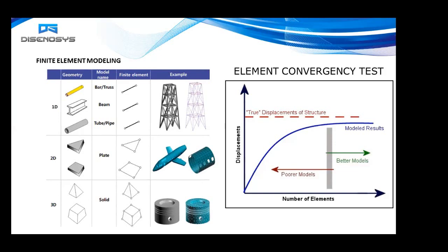Oh, okay, sir. You can't actually cover all the geometry using shell elements. So as we have seen in our example 2, how much you have covered that area, then only your accuracy is increased. So you have to cover your shape initially. How much the possibility of covering the shape will give much better accuracy. Then only your results are also accurate.